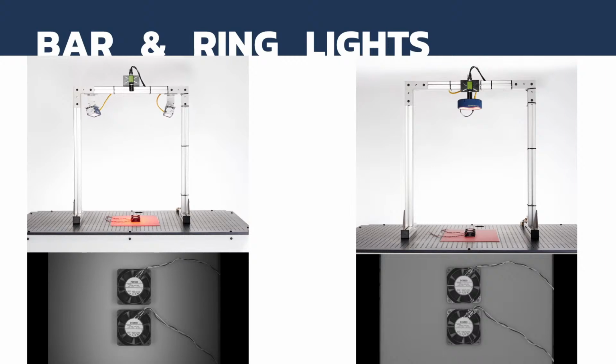In machine vision, we always want controlled lighting in our space for imaging, and having the right geometry of light, as we're talking about, is one of those. And anything that comes from the outside of that controlled geometry is then light pollution and can only hurt us, not help us. So with bright field, both of these are viable options on this kind of object. But let's talk about dark field now.